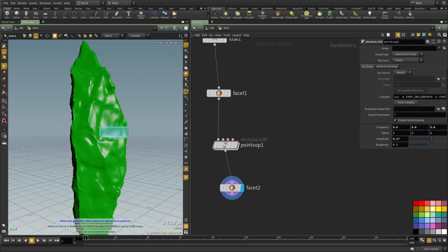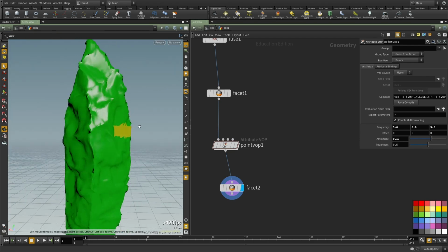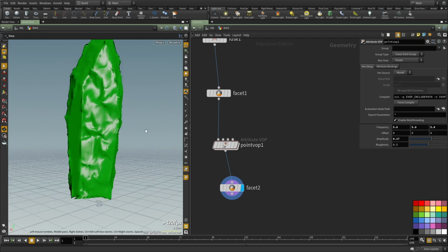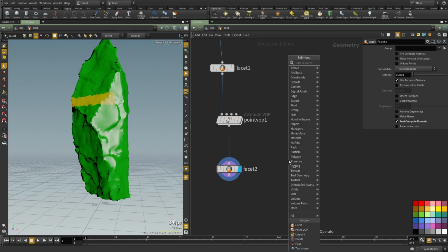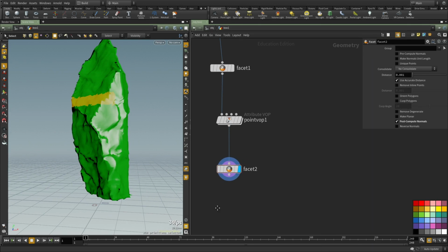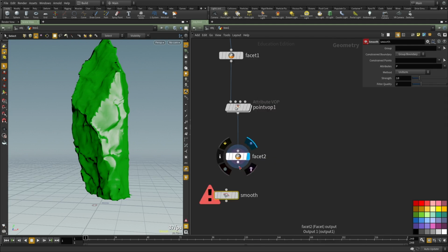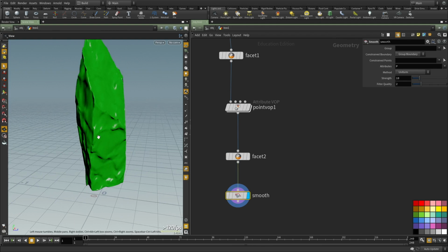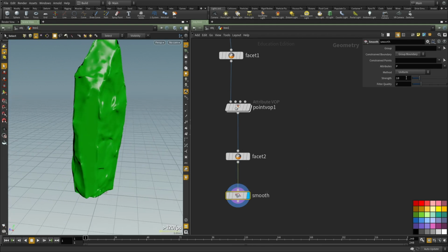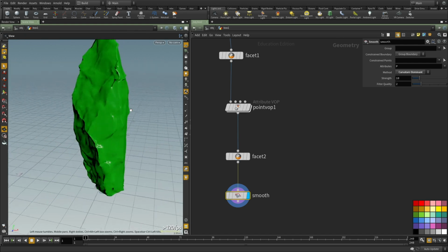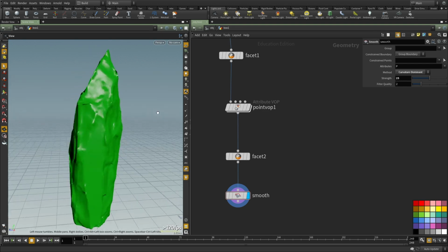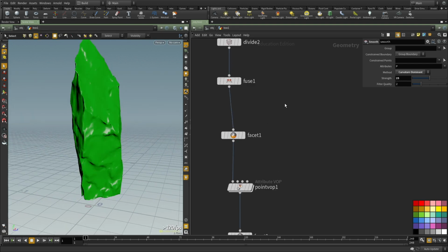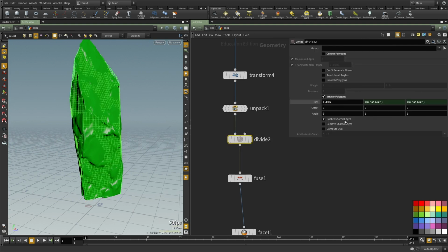Okay, this is what we're going to use to break up the edges, and this will simply work with any method. Now, the geometry, of course, is a little bit deformed overall, but we can smooth that out if we needed to, just a little bit. Actually, I really like what I am seeing, but just in case, if we needed to improve this a little bit, we can add a smooth and use the scale by curvature, and this tends to clean up the geometry quite a bit. And let's add more details. Let's set this to 0.05, so we have a lot more details.